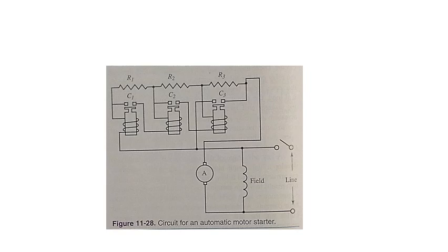The first surge of current in the armature circuit flows through the series coil C1, which holds it open. As the motor increases speed and the armature current decreases, C1 contactor closes and cuts R1 out of the circuit. Similar action occurs in C2 and C3. When the motor reaches full speed, all contactors will be closed. The protective resistance is no longer needed.